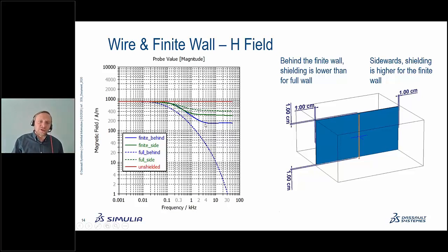of our shielding effectiveness. So this blue curve, which goes nicely downwards, gives us very nice shielding effectiveness. This was just for the wall which was connected to the boundaries. If we make a distance between them so that the induced currents will close inside the wall, then our shielding is degraded.